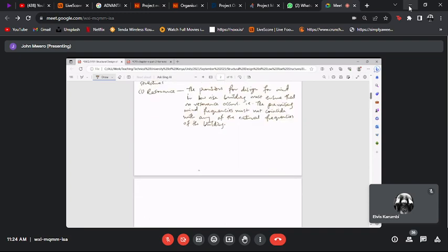The other important consideration for low-rise structures is roofs must be well anchored to resist uplift. Okay, so if you have a roof building like that, okay, you got your elements there for the roof, got walls here.